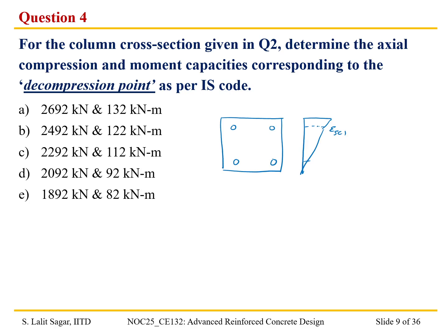This corresponds to the strain in the reinforcing steel, epsilon SC1 and epsilon SC2, and this would be the stress distribution. So the entire block is in compression, a mix of rectangular and parabolic, and we can consider that the resultant is here, Cc.